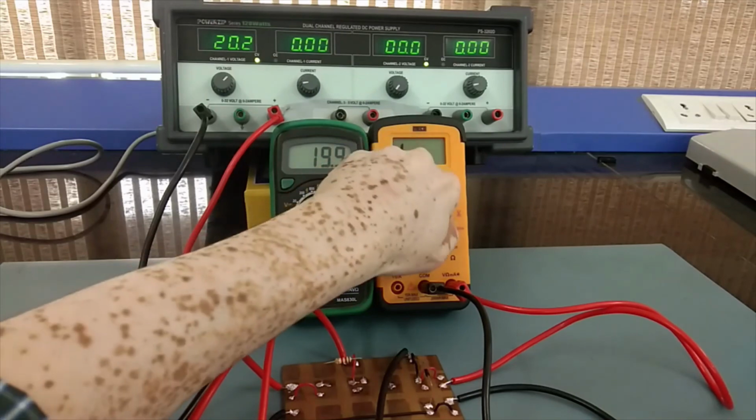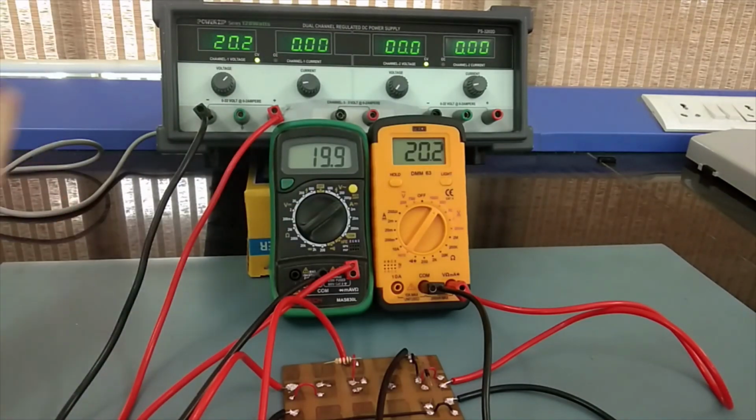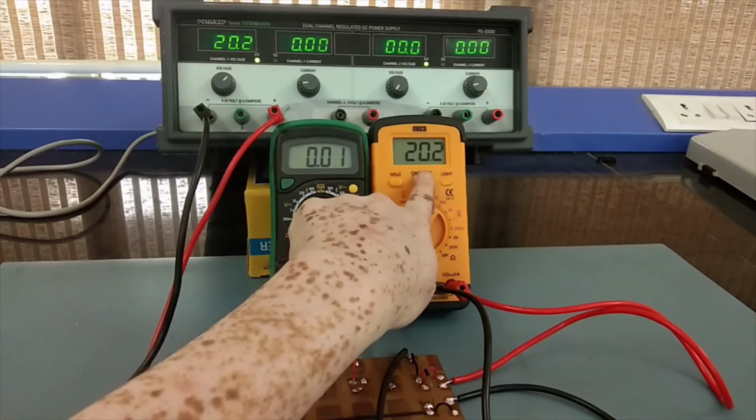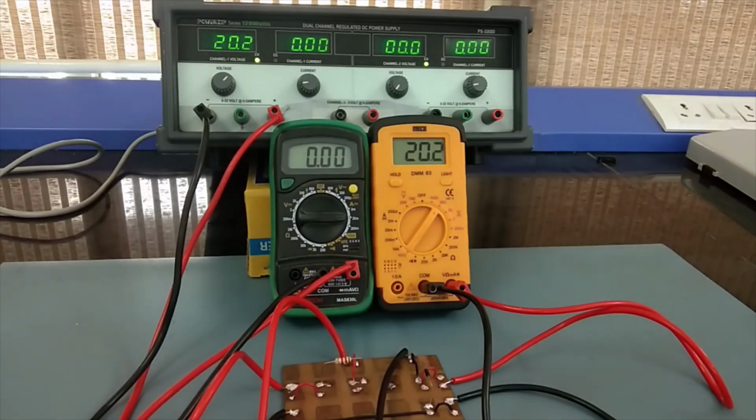and you can see that even now there is no current that is flowing through the diode, which shows us very clearly that in reverse biased condition, the diode does not conduct. The voltage across it increases, but it is not conducting. It will conduct only when the breakdown region is reached, the breakdown voltage is reached. Okay, we are not taking our diode to the breakdown voltage.